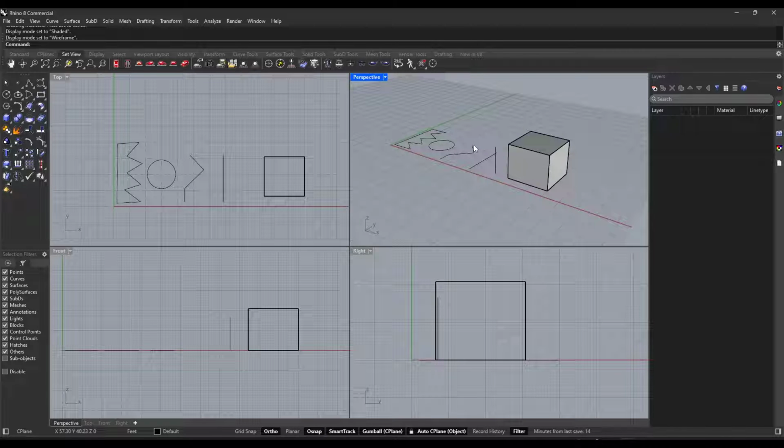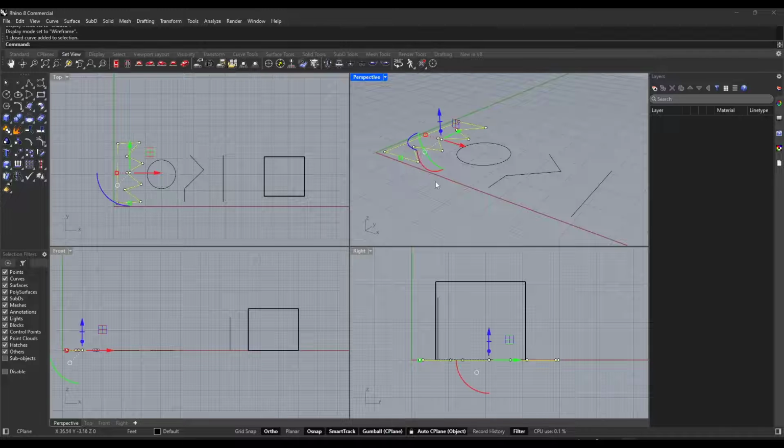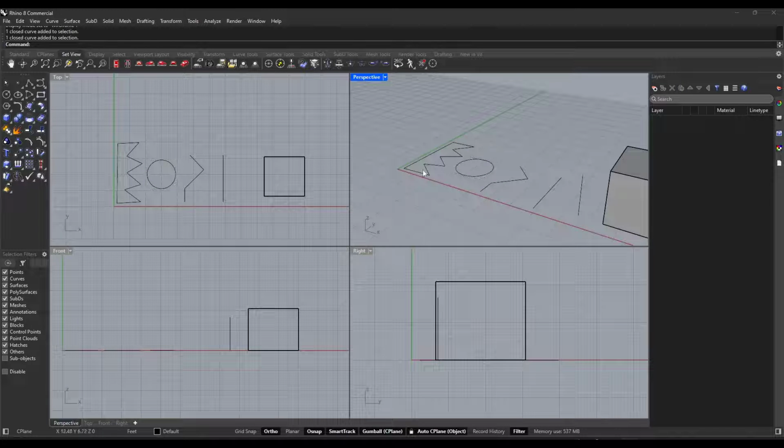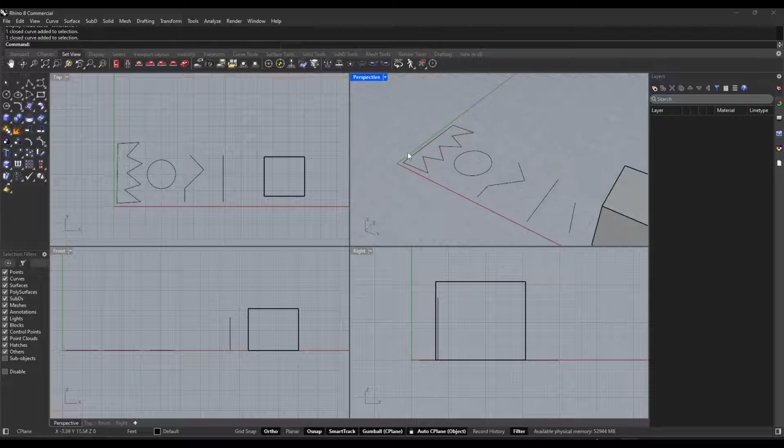Now, let's say that you wanted to draw something more complex than the primitive shapes that are over here, right? More than just like a cone or a torus or a cylinder. Say that you wanted to draw something using this object right here. And so let's say that we wanted to extrude this to 3D. So extruding is basically taking a series of edges and then kind of creating a copy of them and moving them up, but it fills in faces when you do that.